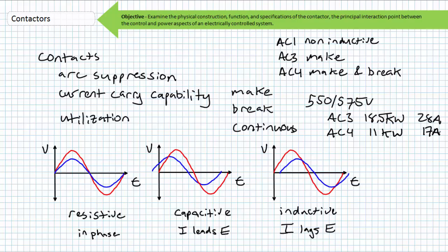The latch coil is momentary in nature, and when energized, simply moves the contacts into a position a mechanical means can then hold them together. The loss of current to the latch coil does not affect the position of the contacts, and they remain closed. Only when the unlatched coil is energized, again with a momentary pulse of current, do the contacts again open.